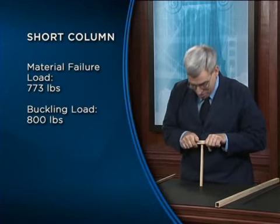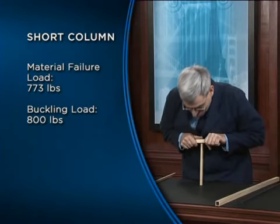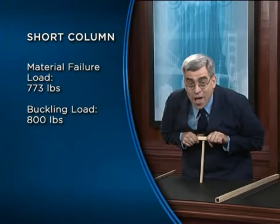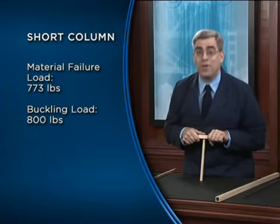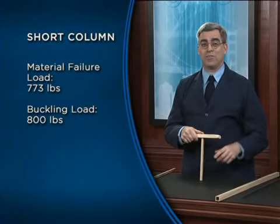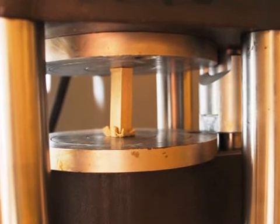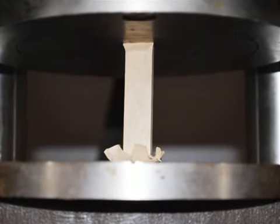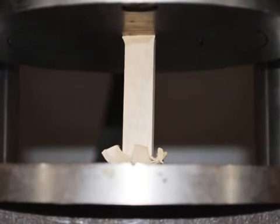In the 4th case, the short column, the material failure load of 773 pounds is less than the critical buckling load of 800 pounds. So the strength of this column is controlled by material failure, not buckling. If I load this short column to failure like this, the material will crush in compression before it fails in buckling. And if I shorten this column any further, say from 6 inches down to 3 inches, I'd get no additional increase in strength because the material failure load doesn't depend on the length of the member.